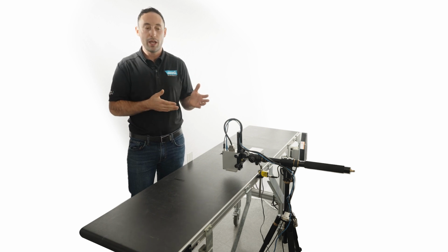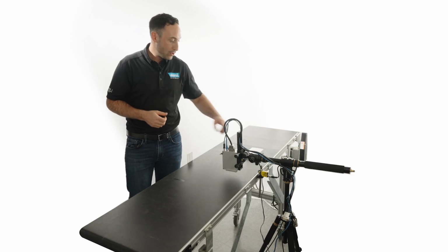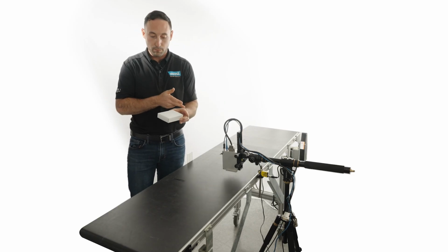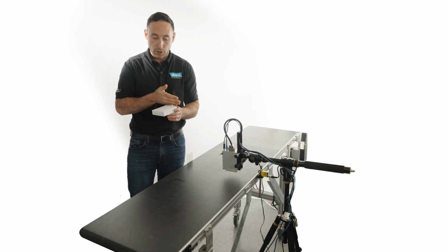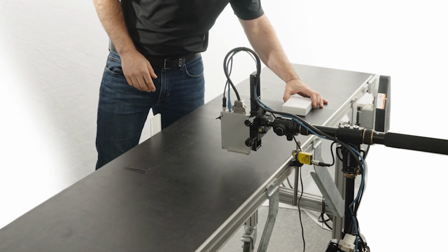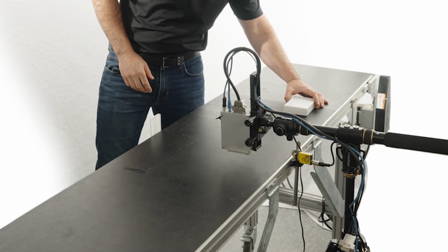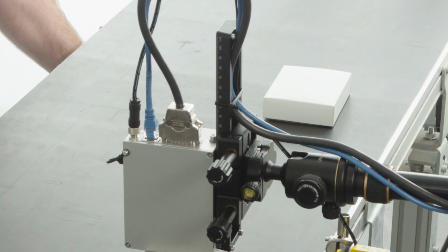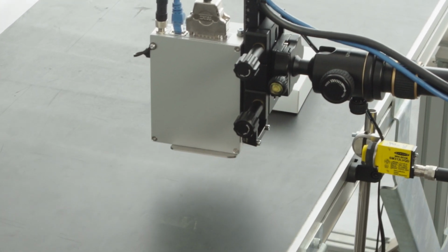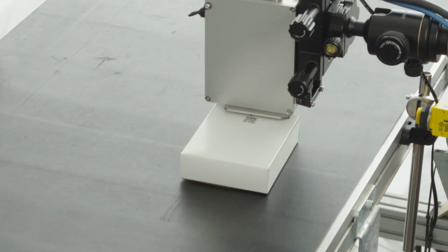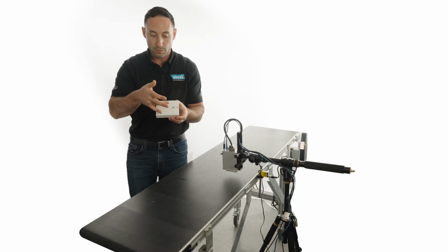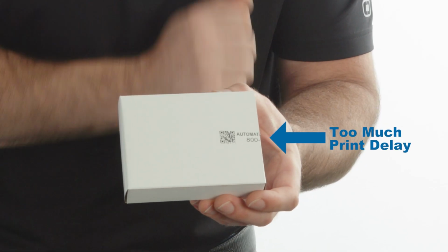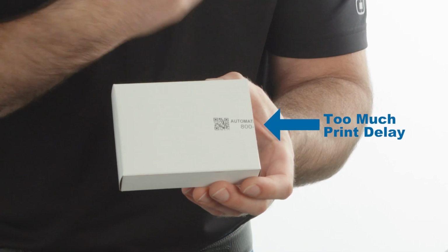So the first prints we made were centered. We had about a 67 millimeter delay. We've gone ahead and increased that. And so that's gonna shift the print back. So when this eye sees it, it's gonna wait longer until when it prints. So let's run a sample and see exactly the effects that we've had. So I'm just gonna flip this on. Okay, so now what you can see here is that before, when the print was centered, now the print is half cut off because it's waiting too long to signal that print.